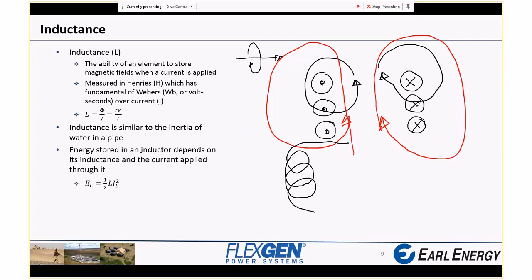Another definition, with probably more physical background than I can understand right now. The energy stored in an inductor is equal to 1/2 the inductance times the square of the current in the inductor. This is analogous to the energy in the capacitor, which was 1/2 C V squared. So that's important. Inductors and capacitors are analogs in that way, and more that we'll see.